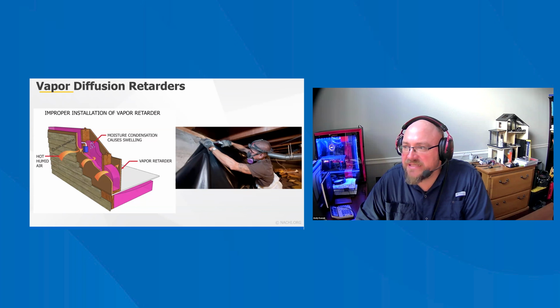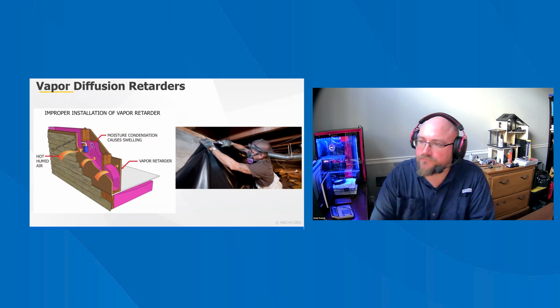The current trend in building science is to refer to materials as vapor retarders, meaning that while they retard or slow down the movement of water vapor, they do not completely halt the process. Materials that significantly slow down the vapor diffusion process are said to have low permeability, or simply low perm. Typical building codes consider a material to be a vapor retarder if it has a perm rating of 1 or less.